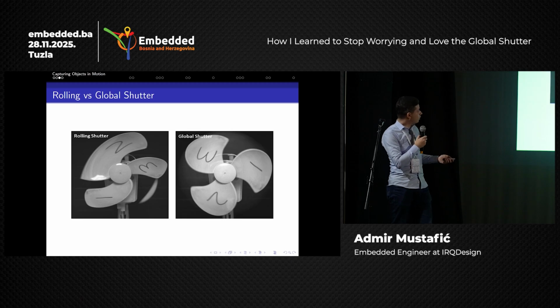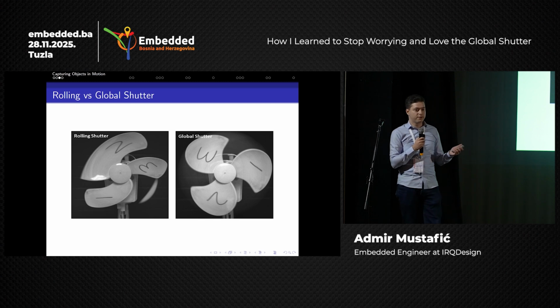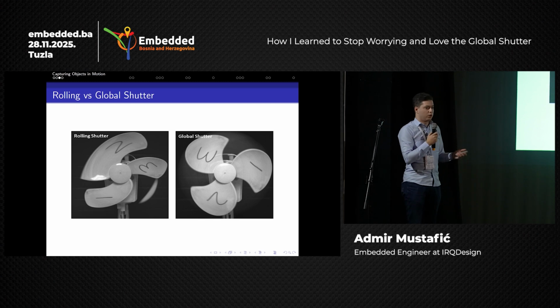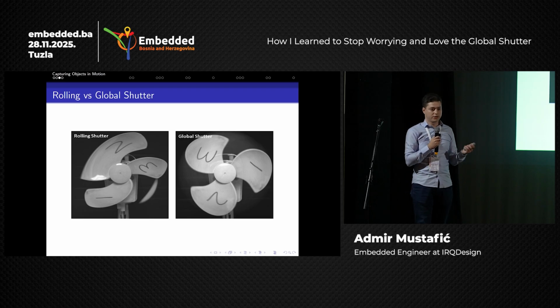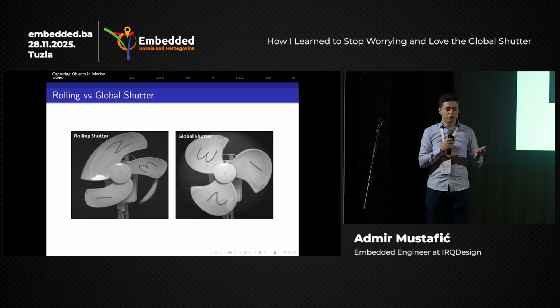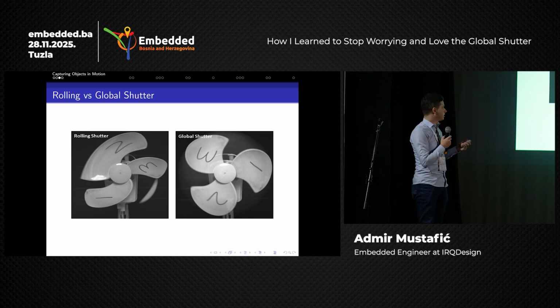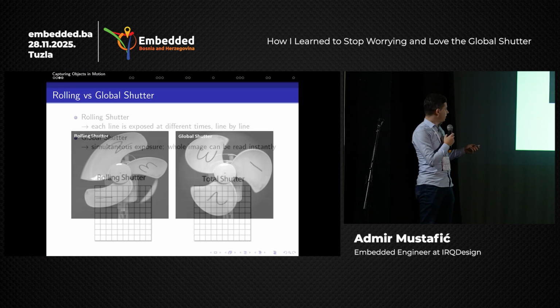And next, we also have the issue of the rolling shutter, which most classic cameras have, but we also have the global shutter, which is present in some cameras but at a higher cost range. The main difference between these two modes, the rolling and global shutter, is how the lines are read. The image lines in the rolling shutter are read row by row, sequentially in essence, whilst in the global shutter the whole image is exposed in one camera cycle, so the whole image is captured.